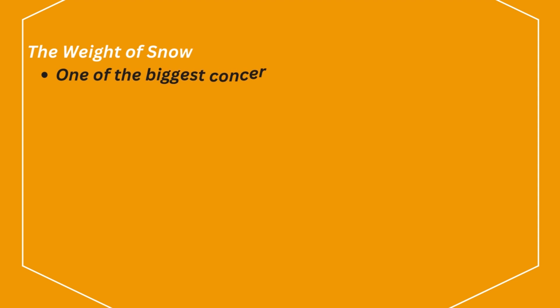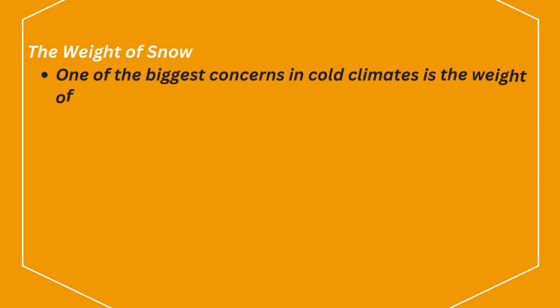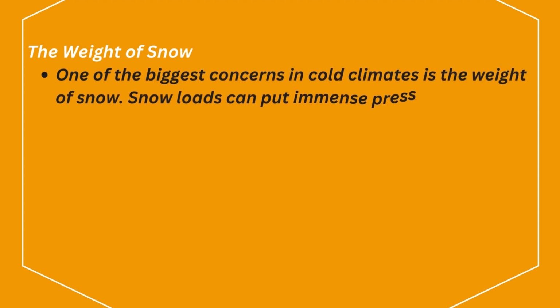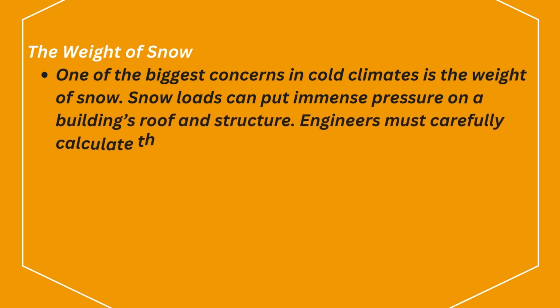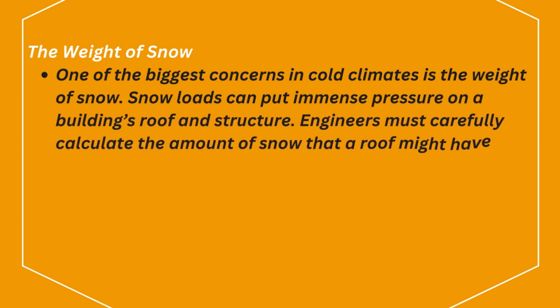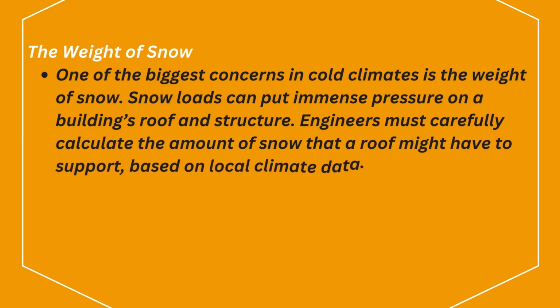The weight of snow. One of the biggest concerns in cold climates is the weight of snow. Snow loads can put immense pressure on a building's roof and structure. Engineers must carefully calculate the amount of snow that a roof might have to support, based on local climate data.